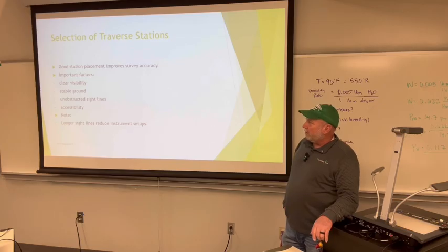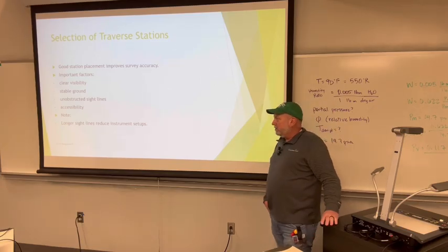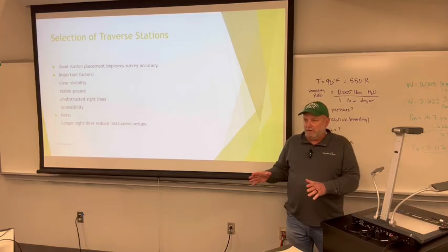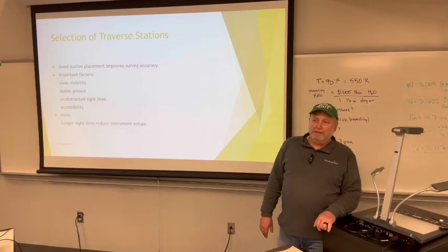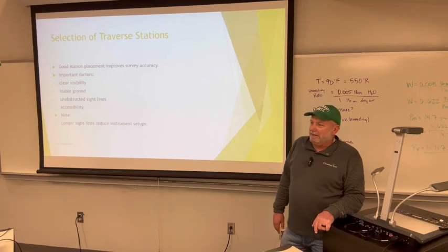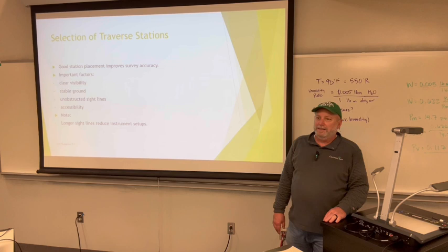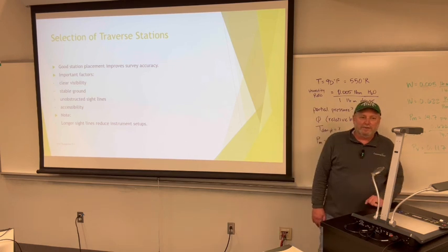Stable ground is very important. If you get into marshy areas or wet, muddy areas, you don't want stuff settling. It's always fun on a construction site when you set the gun up and all of a sudden they decide they need to run a compactor that day 10 feet away from your instrument. That's always a pain in the butt.